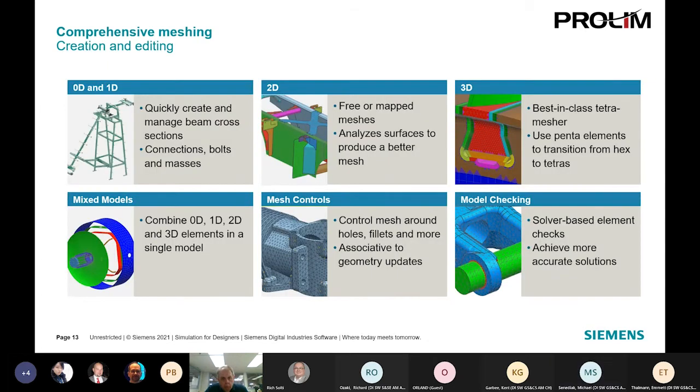Next. So just to give you a quick idea of what those different types are: the 1D mesh is something for when you have frames, piping, tubing, that type of thing, where you really develop the 1D, which is the center line, right? Something like you would do with a sketch. You put that on and then define the type of cross section that goes on that.